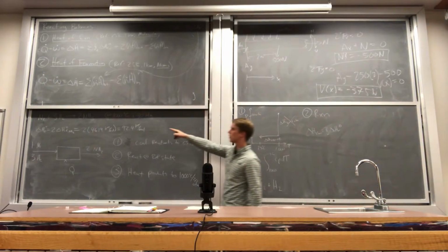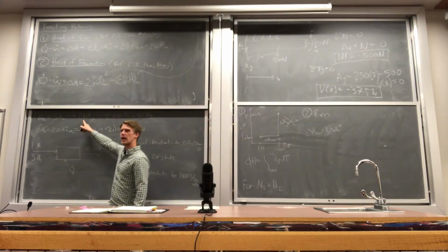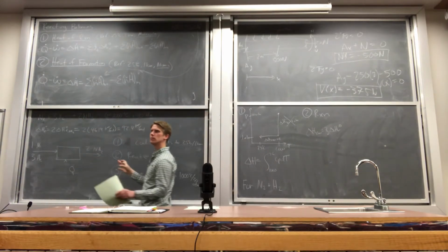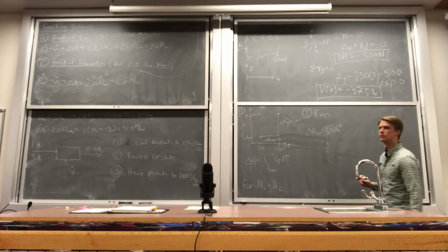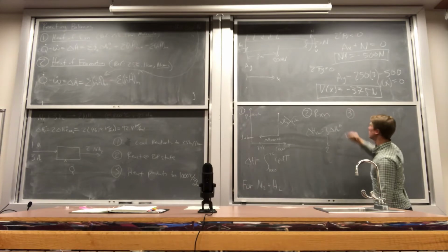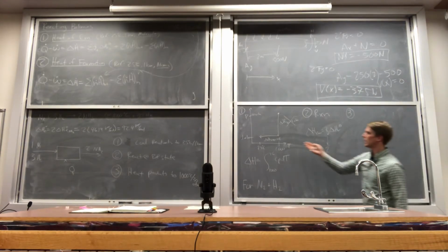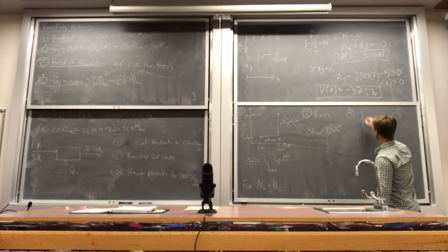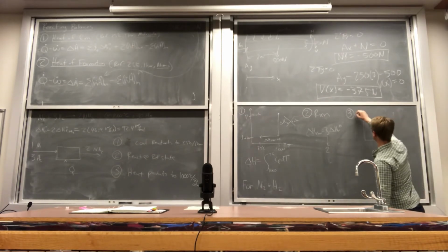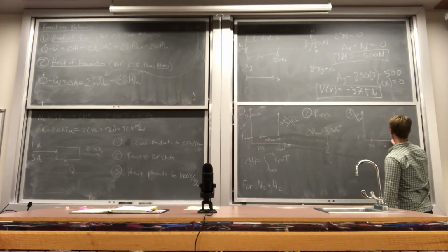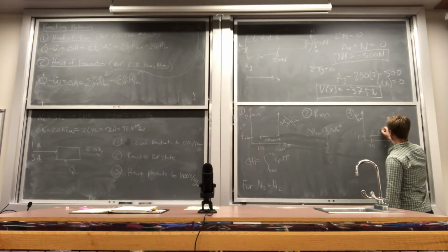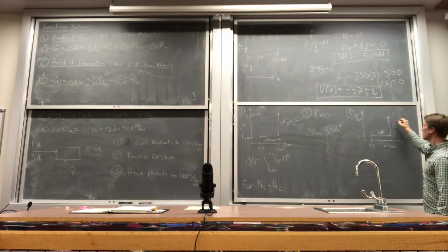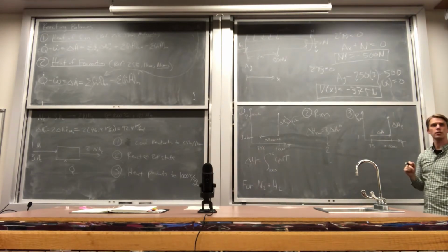So in this problem here, what is my extent of reaction if everything goes to completion? It's 2. And then the third step in the heat of reaction approach is bringing everything back up and going the opposite way. So if we have our PT diagram, we're going from 1 to 30 atmospheres, 25 to 1,000 degrees Celsius. We have a delta H associated with the temperature change, and we have a delta H associated with the pressure change.